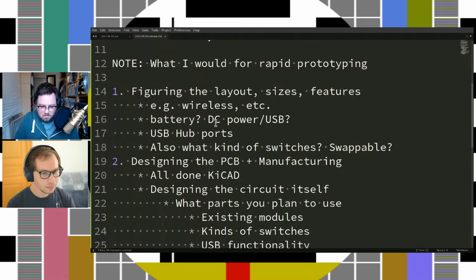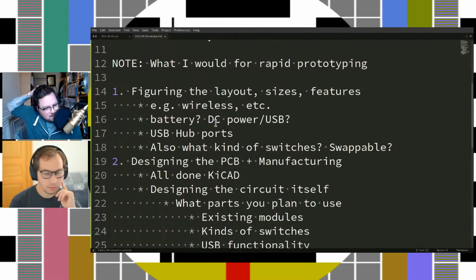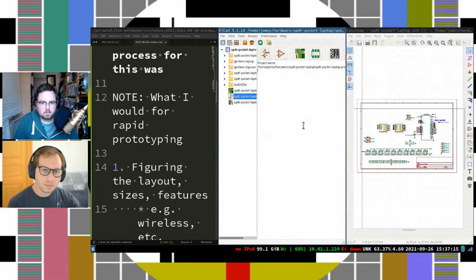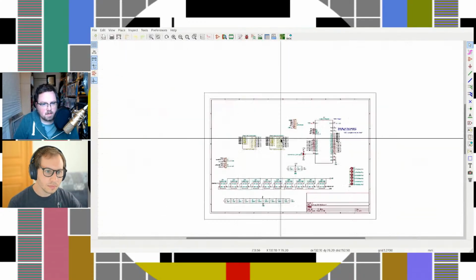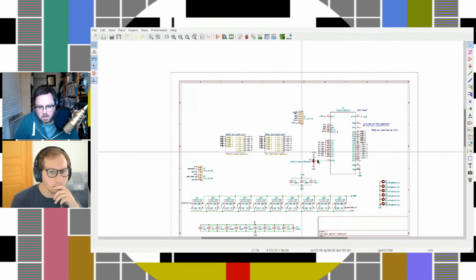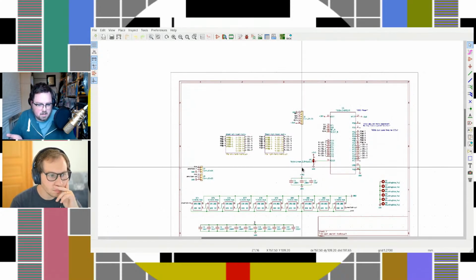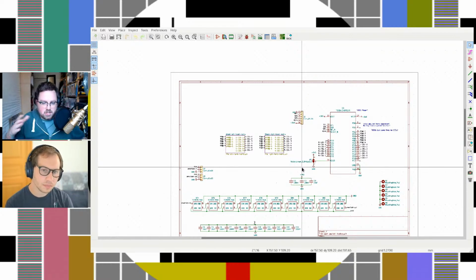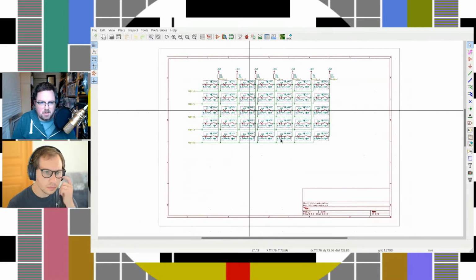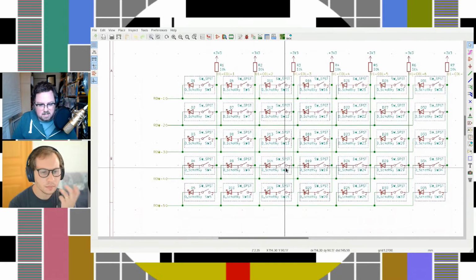Yeah. Let me do another slice of the process that you go through. First, for the keyboard, there are a couple of parts you have to think about. There's basically what your microcontroller is going to be that talks USB. Is that going to be a chip or a module or something like that? Key switches or keyboards have a pretty well-defined set of ways to do them, with different benefits, but the good go-to that I would suggest is this row and column approach.